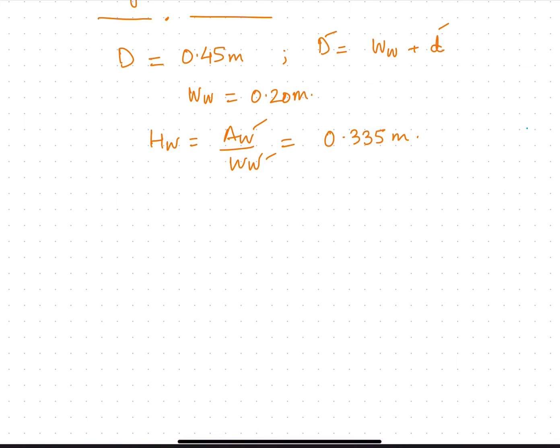And another important ratio that is given to us. Whenever this question is asked, whatever assumptions you have to make, they will be told to you, but some of them you have to think logically. Like for example, the width of the largest stamping A is 0.84 times D. So this comes out to be 0.21 meter.